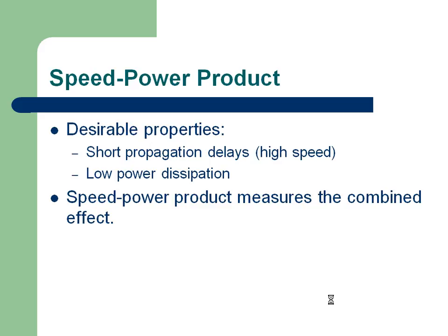You want reduced delay and reduced power. Let us say my gate switches very fast, but I need more power. That is also not a good characteristic. You understand? Or you say I got very low power, but the speed is microsecond. That is also not a good characteristic. So we will define something which is the delay in nanoseconds or microseconds, multiplied with power. This is what we call the speed power product.